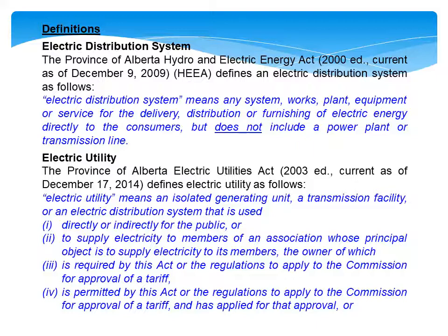Section 2 of the code includes general rules such as prohibitions, restrictions regarding entering facilities, maintaining safe distances, and clearances when working near utilities, building near utilities, or excavating near utilities, and other matters of a general nature. Section 4 in the old editions of the code used to include safety rules. In the 2007 edition, for ease of reference, the safety rules were relocated to Appendix A. Section 4 therefore became not used thereafter.